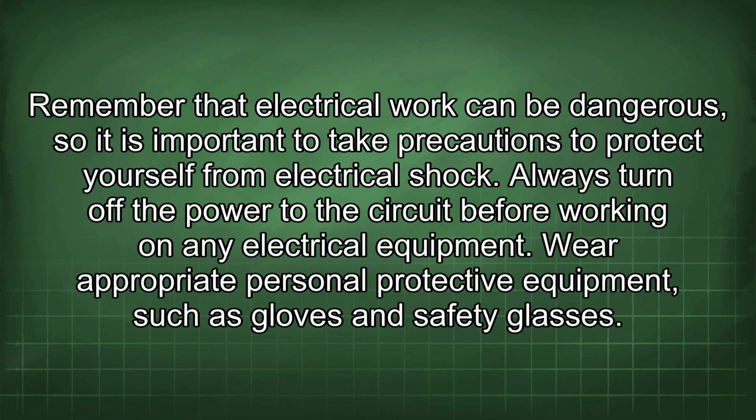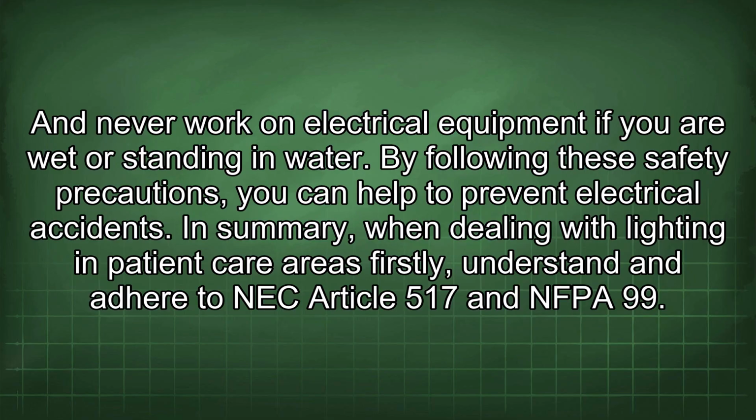Remember that electrical work can be dangerous, so it is important to take precautions to protect yourself from electrical shock. Always turn off the power to the circuit before working on any electrical equipment. Wear appropriate personal protective equipment, such as gloves and safety glasses. And never work on electrical equipment if you are wet or standing in water. By following these safety precautions, you can help to prevent electrical accidents.